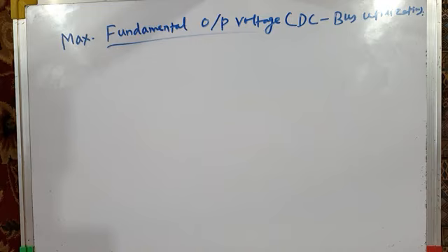In other words, when a particular PWM technique is used, the inverter at its output produces three-phase output voltages. We will see which PWM technique produces the higher or maximum fundamental output voltage. In other words, we will try to understand the DC bus utilization.